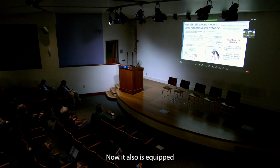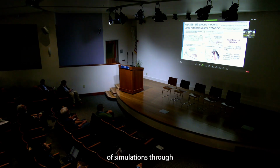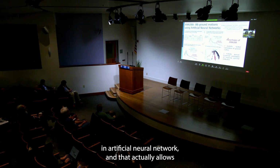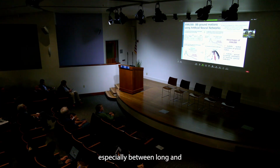Now, it also is equipped with a procedure based on artificial neural network to enrich the low frequency signals that are simulated by the physics-based simulations through hybrid approaches now tuned by the presence of an artificial neural network that actually allows to provide realistic spatial correlations of ground motion and also realistic period-to-period correlation, especially between long and short period spectral ordinates.